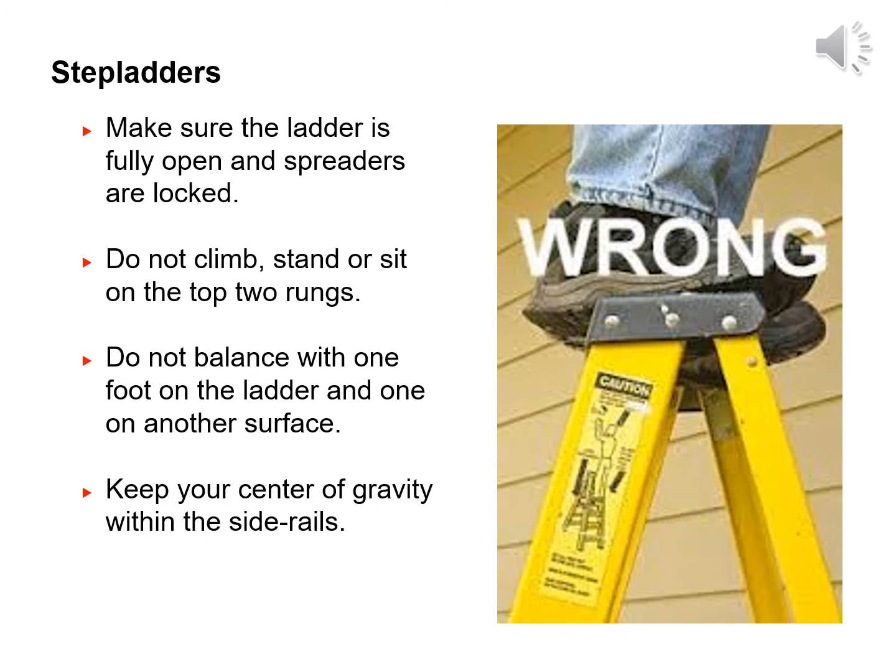Also remember to keep your center of gravity within the side rails. Leaning too far out on either side can cause you to fall. If something is out of reach, you should climb down and move the ladder over.